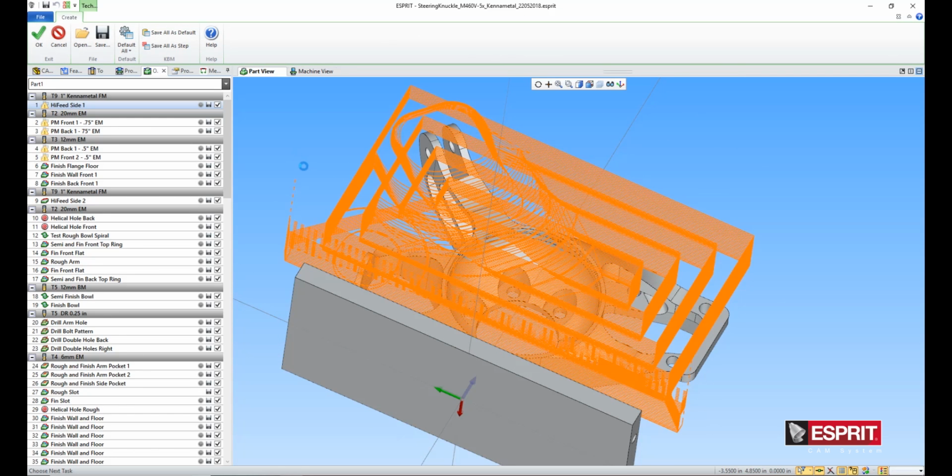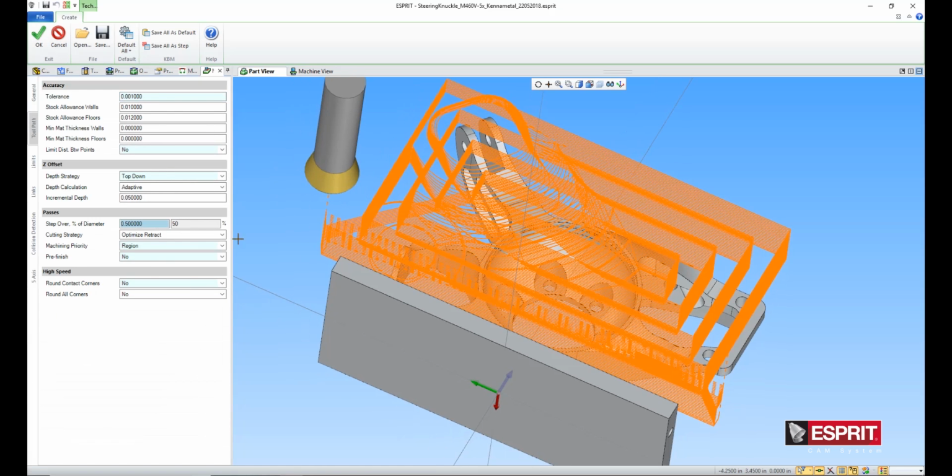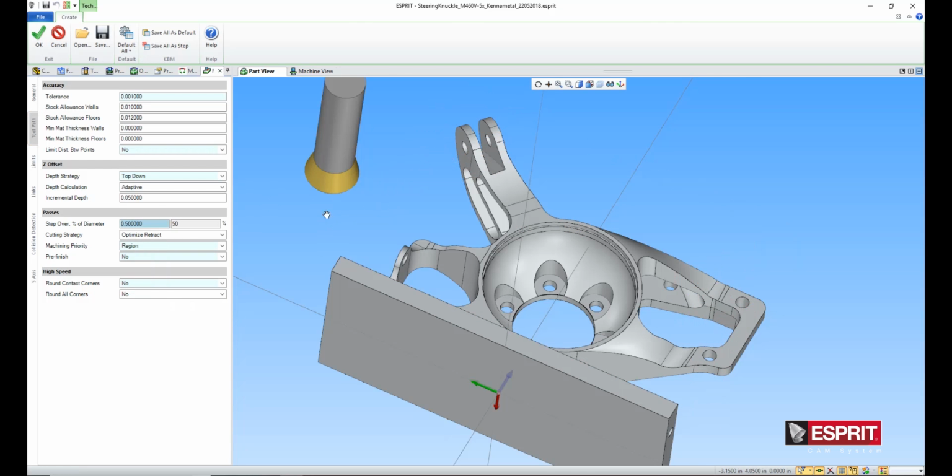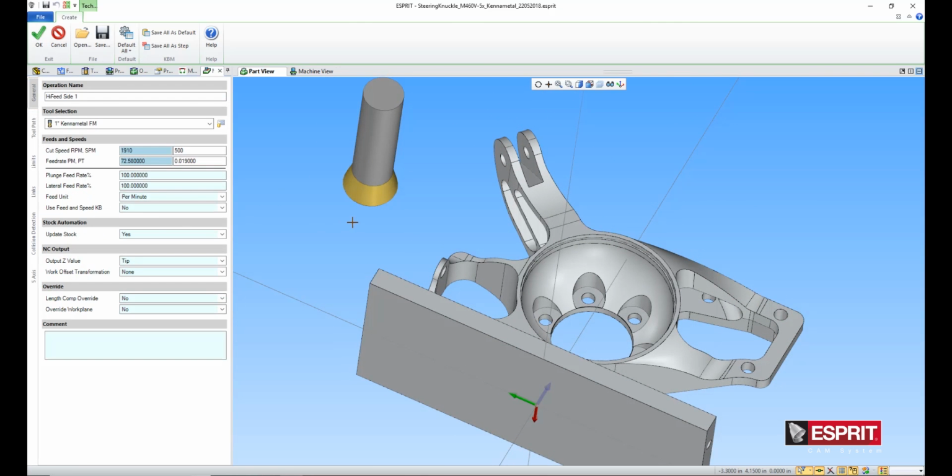The 3D roughing can be done with the Profit Milling cycles, the ESPRIT high performance chip removal cycle. The user can choose to generate the final stock with a quicker calculation process.